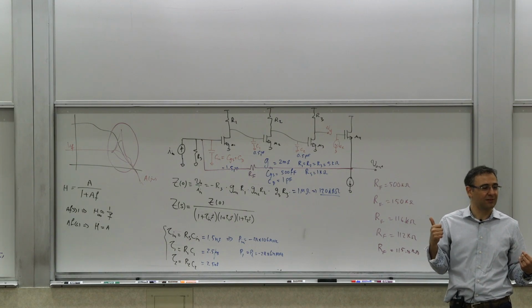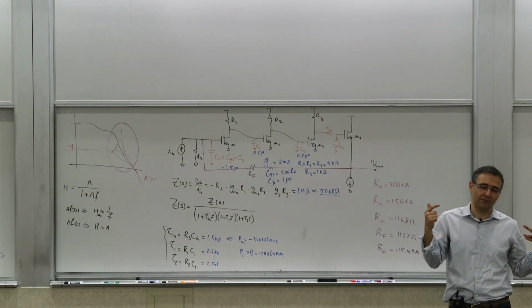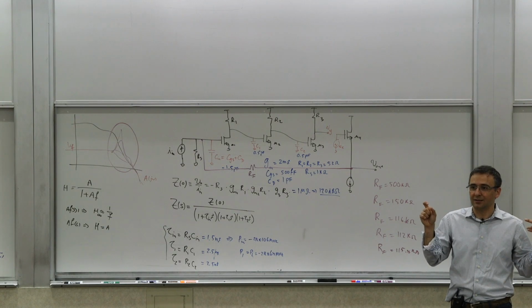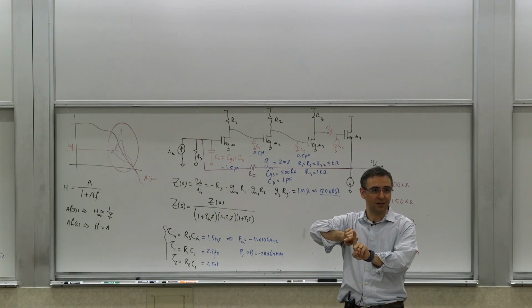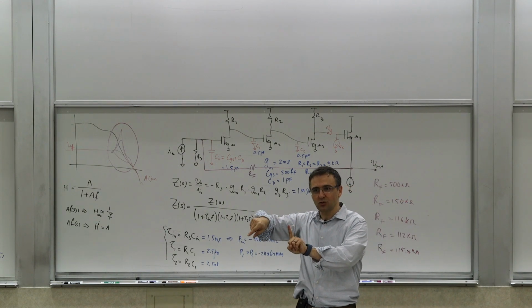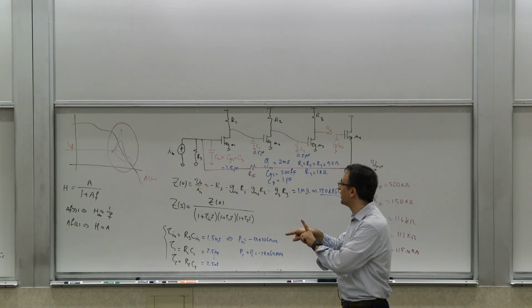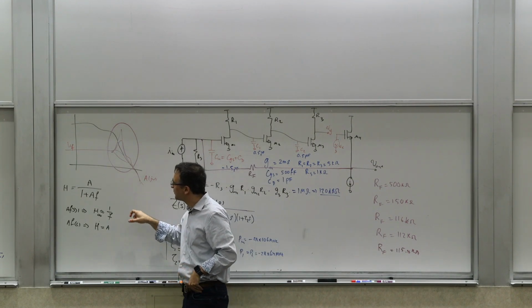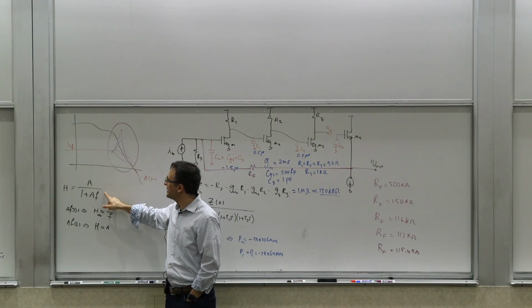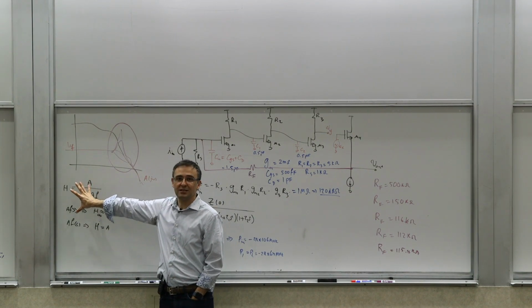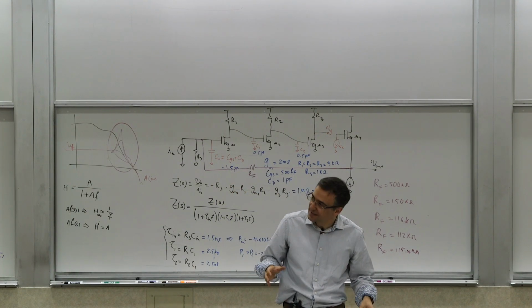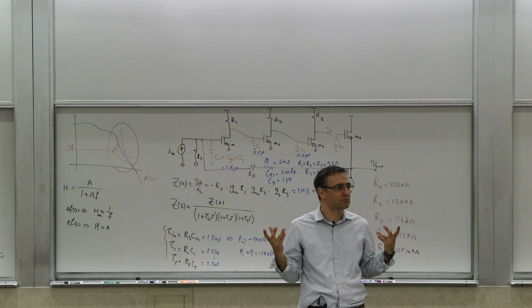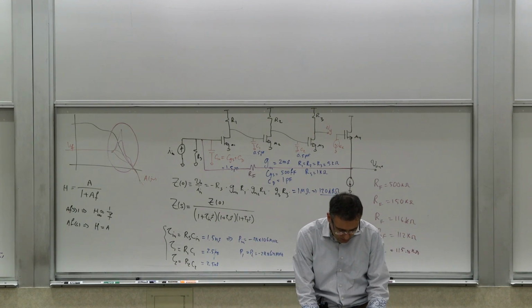So your loop gain, by the way we defined it, or everyone else defines it, is -1. Which means that the signal that goes in comes back. This is a linear analysis right now, right? So if you put a sinusoid in, the same sinusoid comes back. It basically means that 1 plus T, this T has become -1, which means this is kind of like becoming a pole at that point. So that part is not that counterintuitive, right? So far that sounds reasonable.